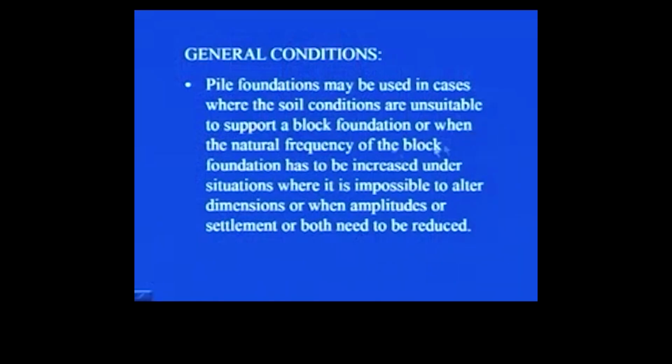So wherever the soil strata is not good enough at the shallower depth, we need to transfer the load at a relatively deeper level where the soil strata is relatively good. So in the case of machine foundation, if the soil conditions are not suitable to support the block foundation, you can go for pile foundation.